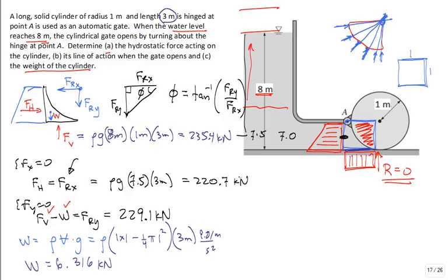So basically I calculate these two components, so I get the F of R maximum, or the magnitude, is the square root of F of Rx squared plus F of Ry squared. And so the resultant force has a magnitude of 318 kilonewtons.